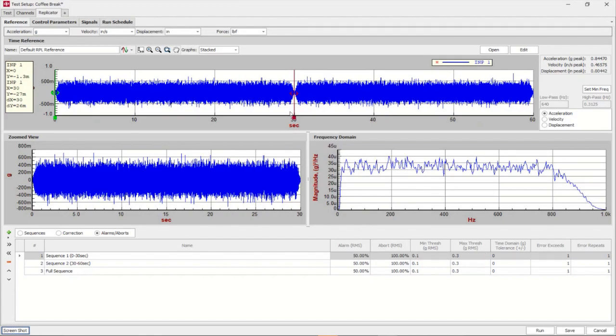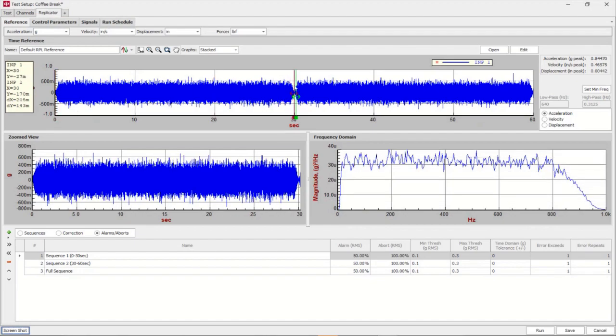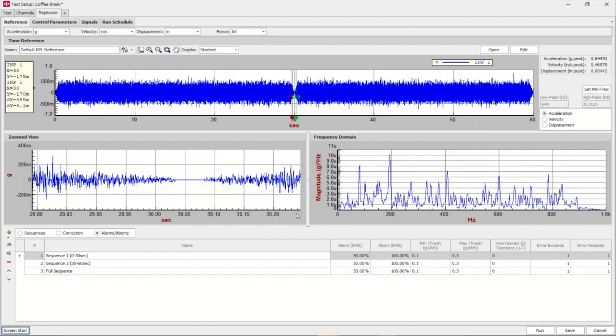What's useful too is for here, when I'm ramping down, let's see between my cursors, it's extremely low amplitude, and I don't care to correct because we're just correcting into the noise floor, and I don't want to waste time trying to correct these small amplitudes. So I can add a minimum threshold here.